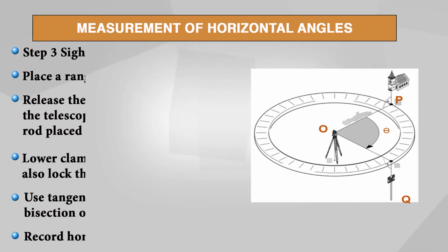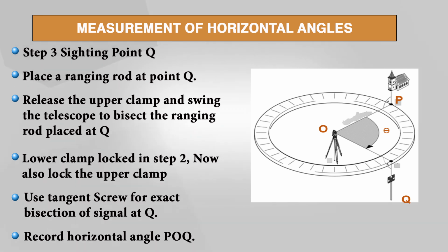So, the key point is, when you want relative displacement between the plates, we have to loosen the upper clamp. Okay, moving ahead, when we loosen the lower clamp and turn the telescope back to point P, remember that this is a repetition method.